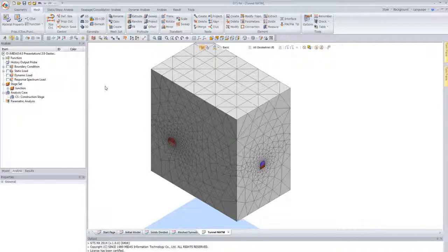How is it guaranteed? So the Shotcrete elements are extracted from the face of the tunnel solid elements, which is demonstrated throughout the GUI and the user interface. So the nodes are automatically created coincident between the two in the same place.